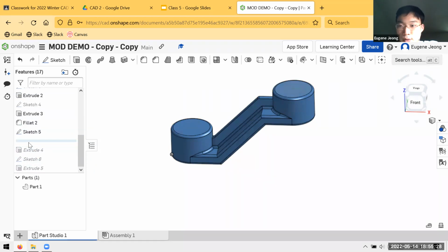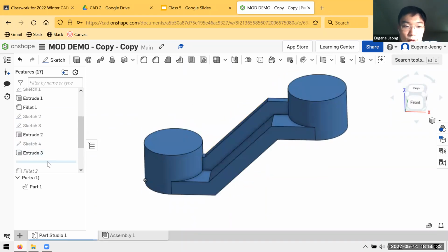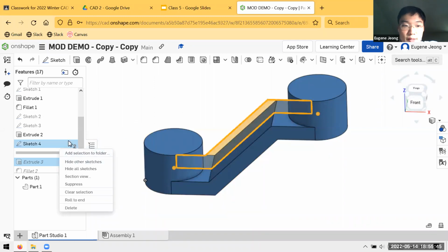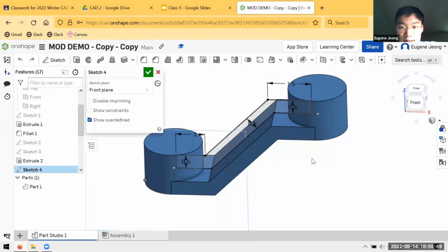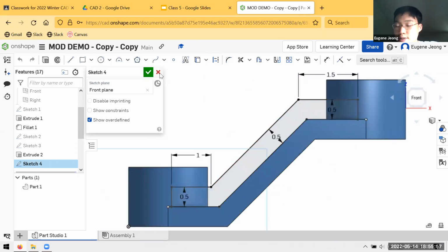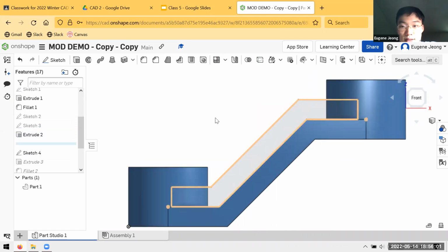So I just rolled back the two holes that I made. I roll back this fillet, I can see what that fillet was doing. I can see, oh, that extrusion was doing that. So that's kind of relevant, right? But this feature has that angle built into it. When I look into the sketch, let's see what I find. Basically what I see is that this sketch is defined off what's already there. So the angle isn't built into this sketch. It's built into something earlier than the sketch. So I have to keep going backwards.